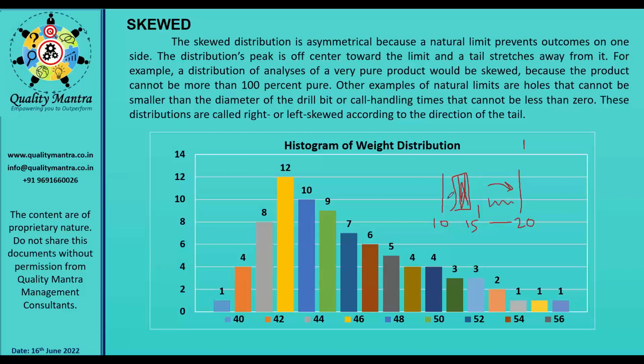In this case, when you analyze it on the histogram, you will see a pattern like this, and you will come to know that many of the data are nearer to the lower specification limit. It is acceptable, well acceptable. But what happens, the capability is lower in such cases. The chances of that product going out of specification is more. So you need to analyze the data first, then analyze its capability, its performance, basically PPK data, and see whether it is meeting your PPK requirement or not.